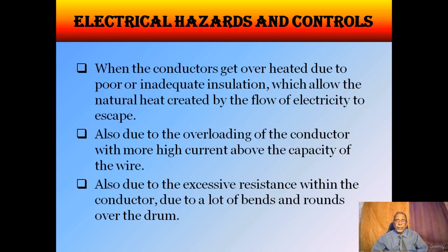Another reason for fire is when the conductor gets overheated due to poor or inadequate insulation, which does not allow the natural heat created by the flow of electricity to escape. Another reason is the overloading of the conductor with high current above the capacity of the wire. And another reason is excessive resistance in the conductor, due to a lot of bends and rounds over the drum.